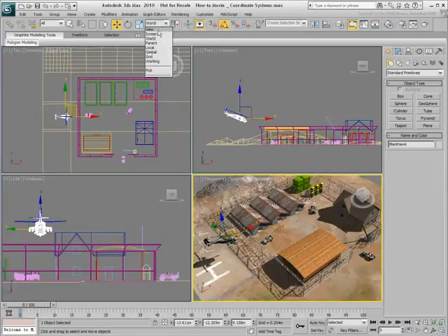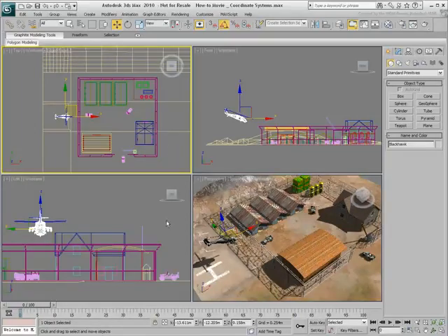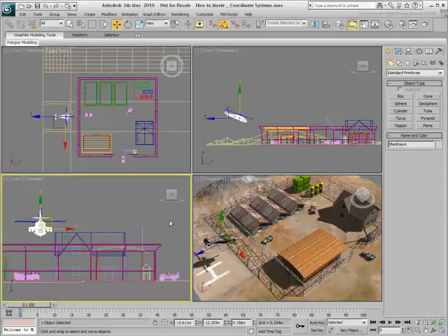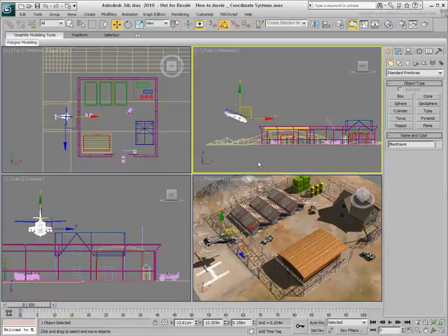As you transform objects in the scene, you're more likely to use the default view coordinate system. View works like world if the active viewport is a 3D view like perspective, but in orthographic views, the axis tripod reorients itself so that you're always facing the XY plane. This simulates working in 2D in an orthographic view, where the XY plane always runs parallel to that view.